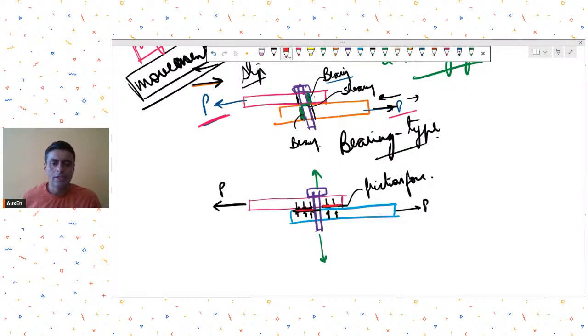You understand? So now in this case, even if my hole dia is slightly larger than the bolt dia, because the resistance is provided through friction transfer, there will be no slippage. Are you clear? No slippage in the connection.